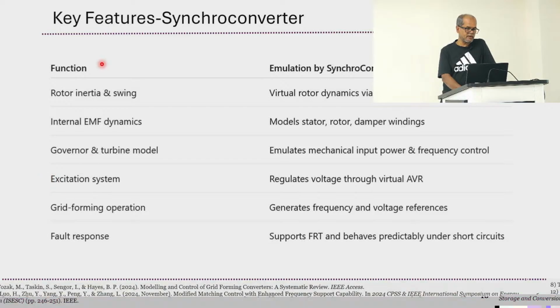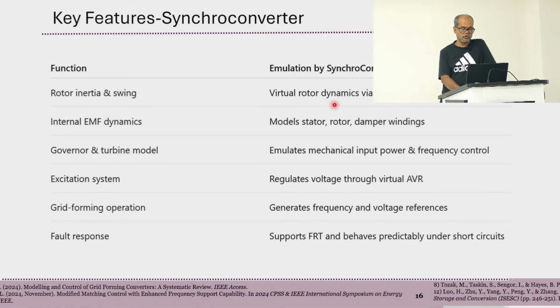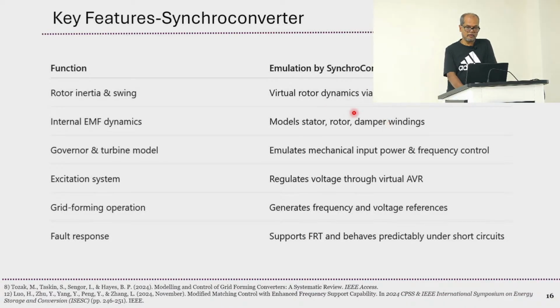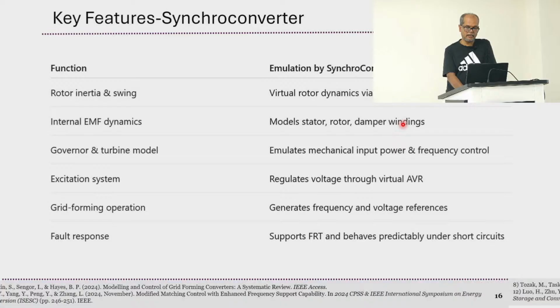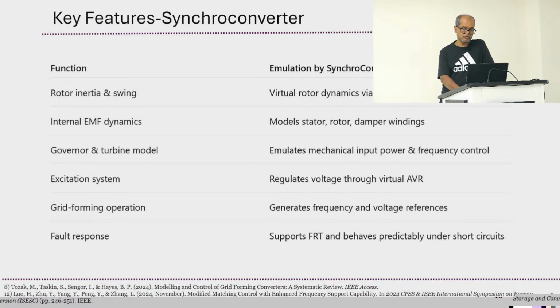Everything that's part of the synchronous generator is considered and provided through this synchronverter, including virtual rotor dynamics, everything happening inside the damper winding, and mechanical input frequency, because the governor normally regulates this. Normally in a synchronous machine we use an AVR, automatic voltage regulator, and that is also included here in the synchronous converter.